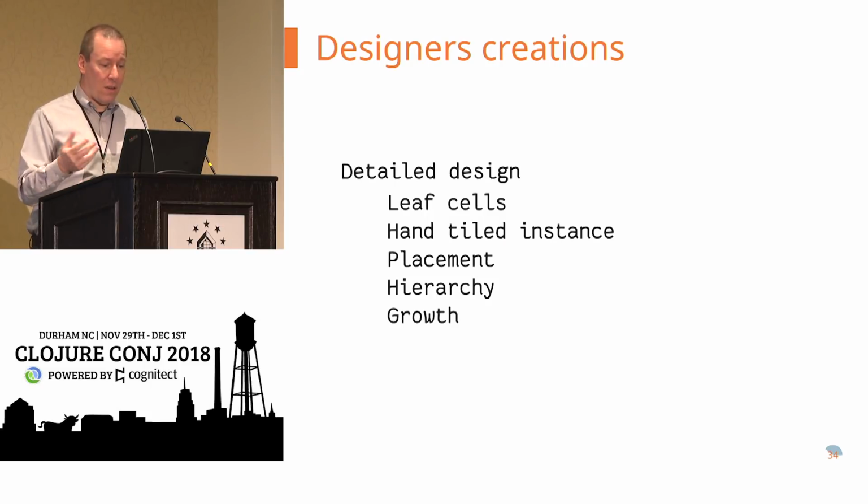And that design includes the leaf cells, maybe a hand-tiled configuration, which is used for exploratory purposes. But ultimately what comes out of that is an understanding of what your hierarchy is, how things get placed, and an algorithm which describes how things are going to get placed as you parameterize, as you grow the memory design to different sizes.